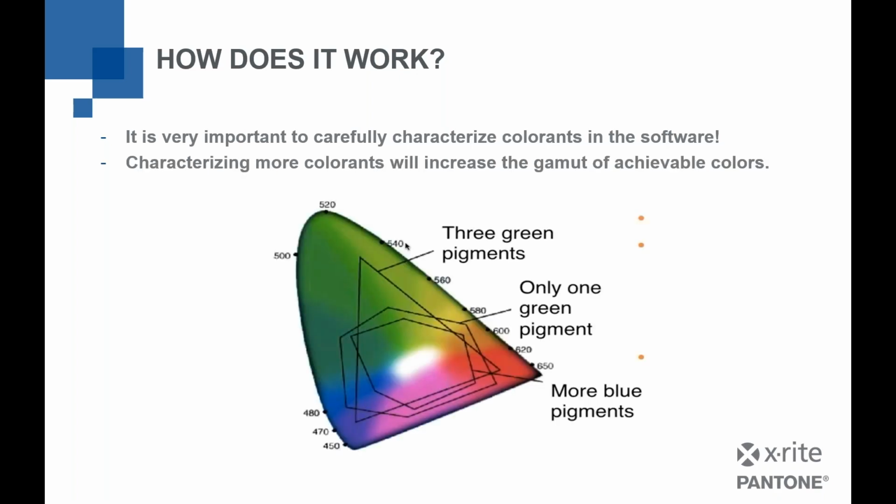All right, so we're using math. The more math points you have, the bigger the gamut of the colors that you can achieve. A gamut, in its very simplistic form, is the size and color space of all the colors that you can actually achieve with your pigment system. So the bigger gamut you have, the more pigments you characterize, the more colors you'll be able to match. For example, in a retail paint store, they generally have 12 to 15 colorants that they use, and so they have a fairly wide gamut of matches. It really depends on your process and your pigment supplier, but we're trying to get as many pigments as we possibly can. And the computer would tell you or help you figure out which pigments to use to achieve a certain match.